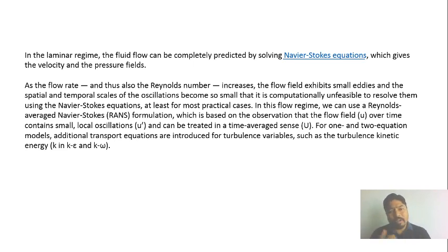But when we are going to solve a problem related to computational fluid dynamics, like in turbulent models, we need to consider the fluctuation in the velocity parameters. If you remember, go to your previous lectures about the Reynolds decomposition or the Reynolds stresses, where we decompose our velocity component with respect to time, taking the average velocity from that flow region, which is denoted by capital U, and the fluctuating velocity, which is denoted by U dash.